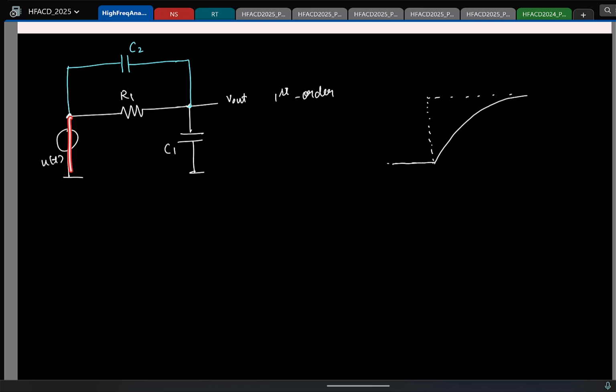They are in parallel. Essentially you can only initialize the voltage across one of the capacitors, because when the input is shorted, the voltage across the other capacitor is also defined automatically. So only one initial condition can be defined independently. So first order system. But do you have a 0 here?